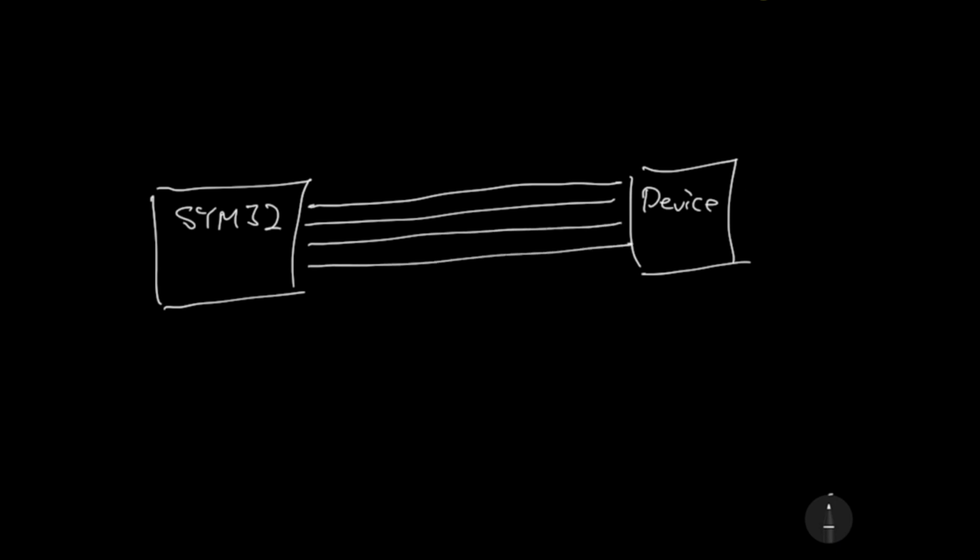So the first one which we are going to need is our chip select line. Now you'll sometimes see that one written as NCS, and part of the reason for that is because that chip select line is an active low signal, which means that it's typically going to be high, but the signal will actually go low when it goes to communicate with that particular device.